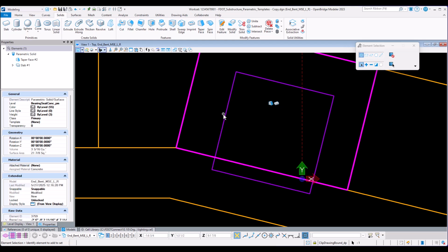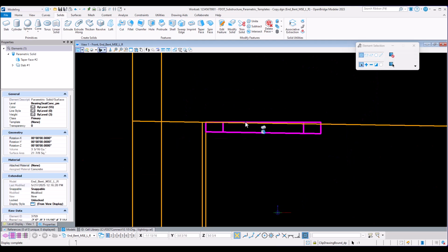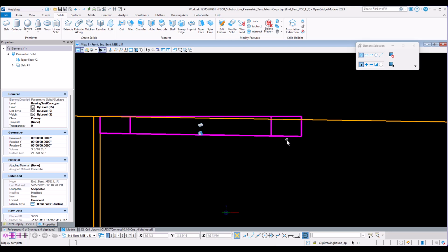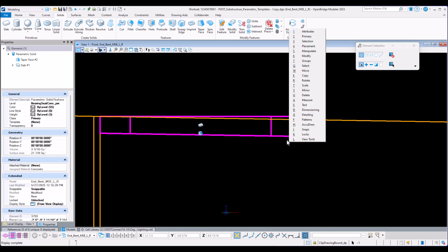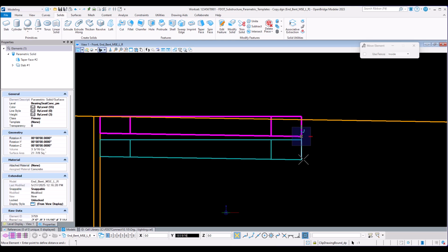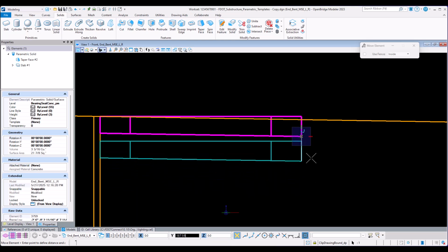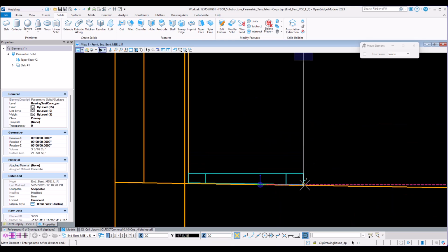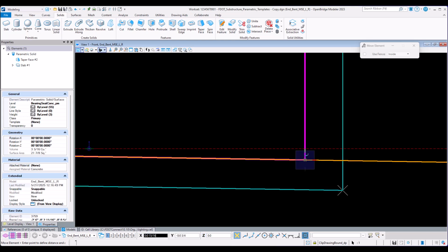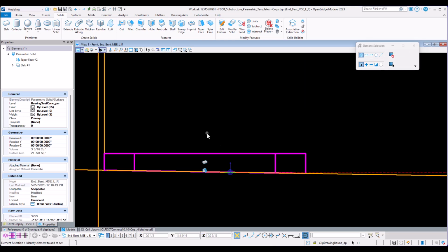And then from there, we're going to switch to a front view, shift right click F for front. We need to get that pedestal in the right spot elevation wise. We already have that pedestal selected, so we can do a QW for move and snap from a corner point. Enter to lock in that AccuDot compass in the vertical direction here. And all we need to do is zoom in and snap to the top of the cap there. And now that's going to be in the correct position vertically and horizontally.